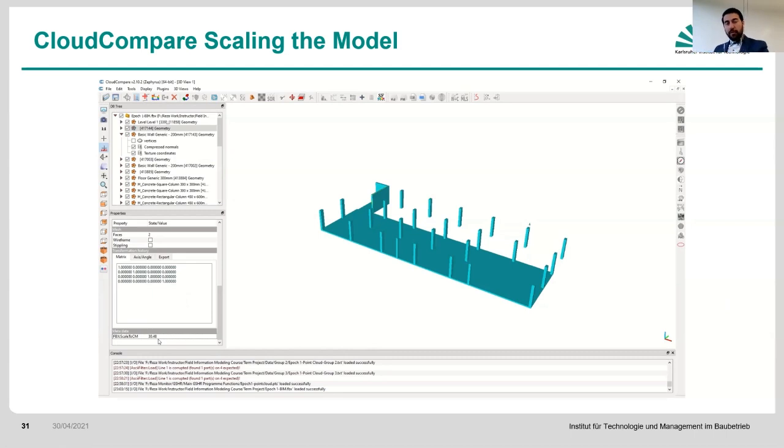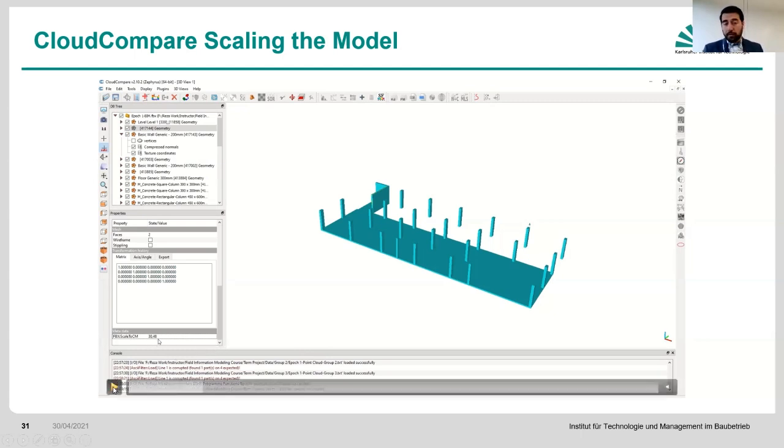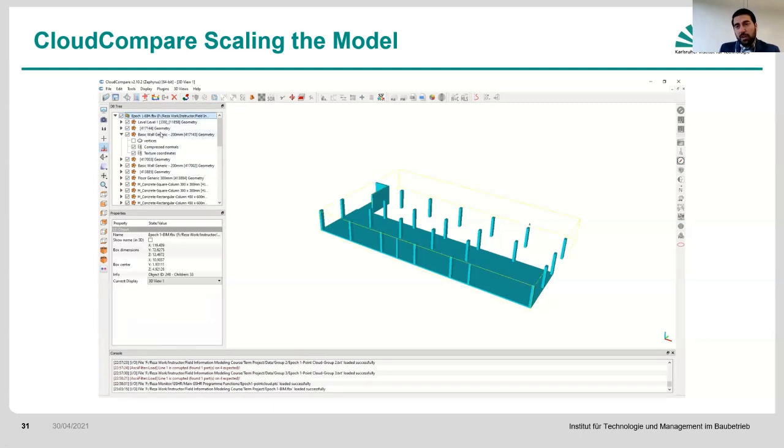This is mostly because, for instance, you have your BIM in, let's say, inches. When you're converting it, it's not as interoperable, even sometimes if you do it properly. This shows that it was in inches, but it's really in meters that you're supposed to have it. So you need to rescale this in order to see a proper comparison with what reality would be. So you're going to use 1 over this scale: this is scale to centimeter, and you want to have scale to meter.